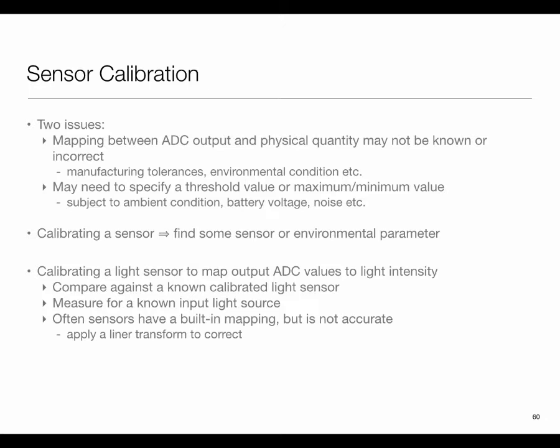For example, you buy two weighing scales from the same manufacturer, stand on one, stand on the other, you'll have different errors, right? So sensors need to be calibrated. For that specific sensor, you have to map the physical value into the corresponding electrical value, or the eventual number that you get out of it. The reasons are many: manufacturing error, environmental conditions, aging. Sensors change over time, because in a weighing scale it could be the spring tension changes over time. In a chemical sensor, the concentration changes over time. All those kinds of things can happen.